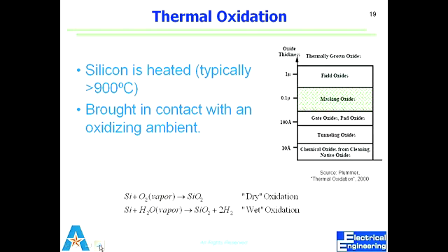In dry oxidation, we have just oxygen, and in wet oxidation, we have water vapor used during the silicon dioxide growth. That extra hydrogen results in higher porosity silicon dioxide. So it has more porosity, which changes its etching property and its electrical properties.